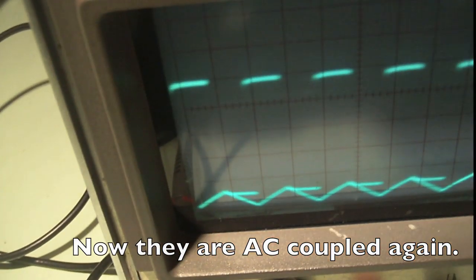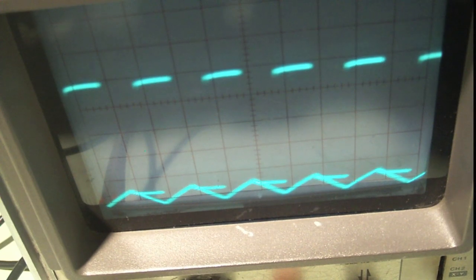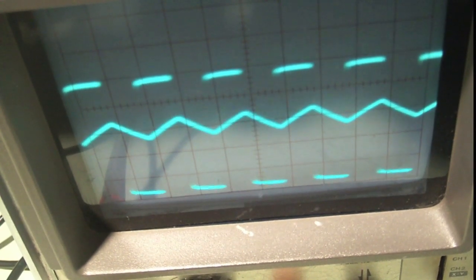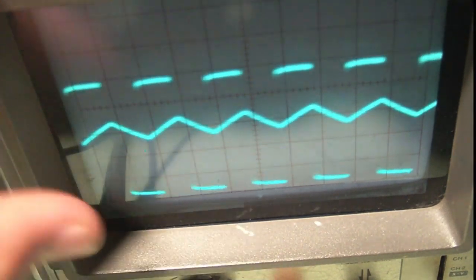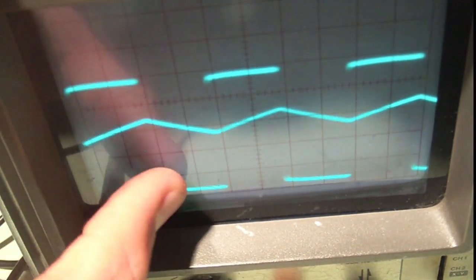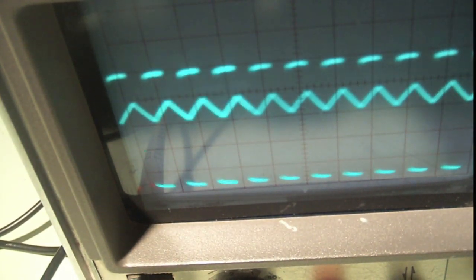Our goal is to get a voltage in the middle basically. So this signal would be in the middle. Okay, but there's a few things that you're going to notice. Actually, I'm going to set that to DC couple to notice. One of the first things is that, you probably can see that better, is that we have about a volt of ripple on our signal, okay?